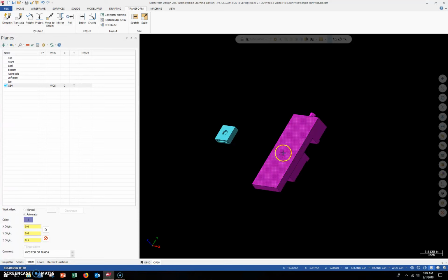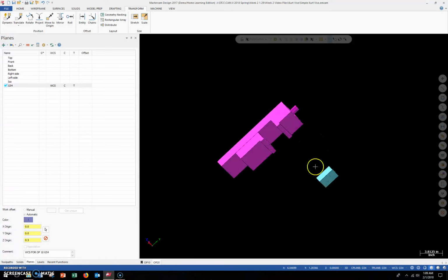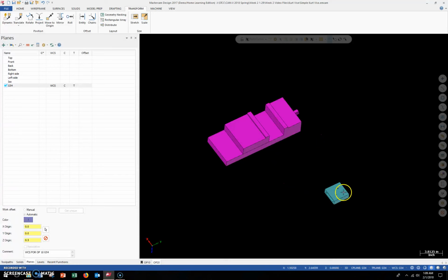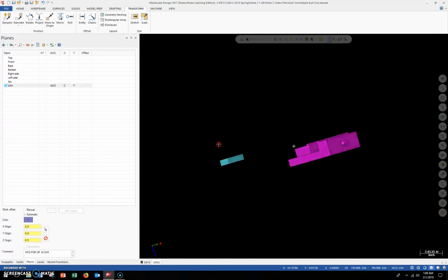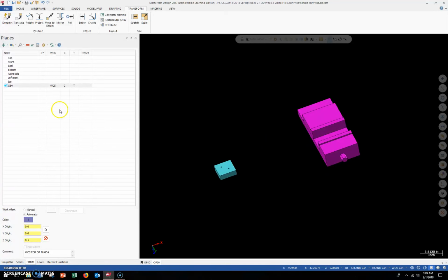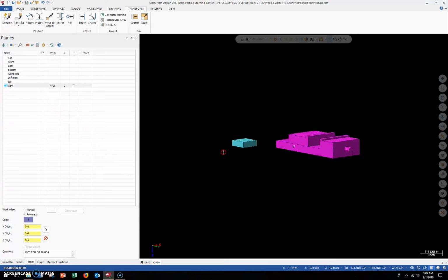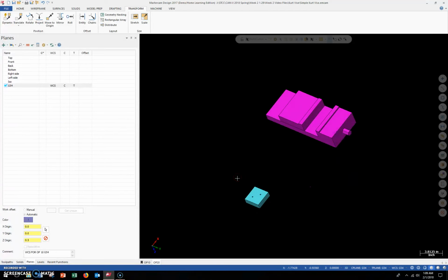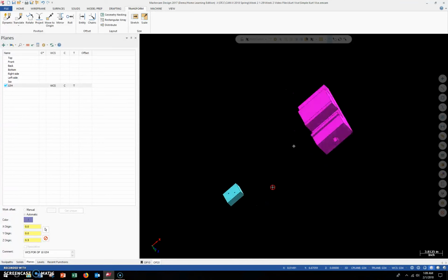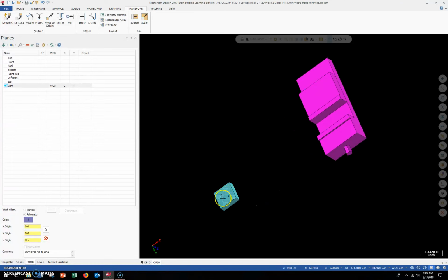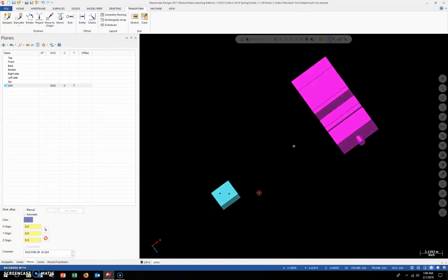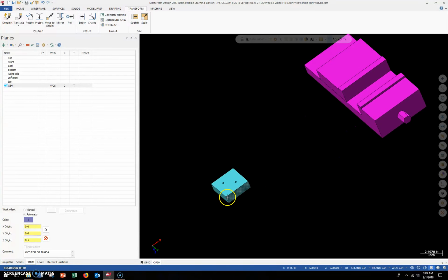The vise is going to be in position to basically hold the part so that this is facing top. What we're going to do now is create our next plane and position that here on the part. I rotate it around so that I can get a clear view of the corner that we need. We want to do the bottom left-hand corner of the part again. In this case, we're going to locate our new plane right here.